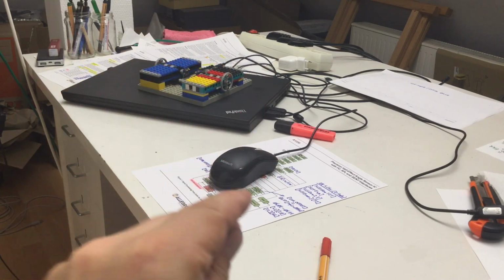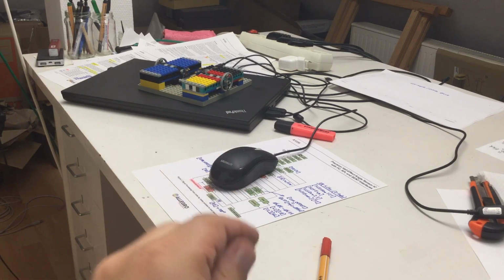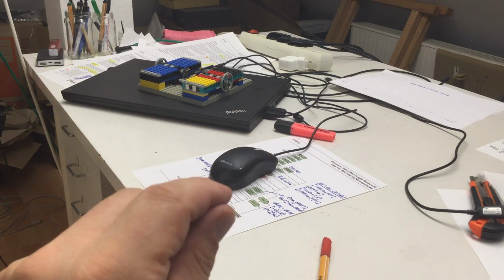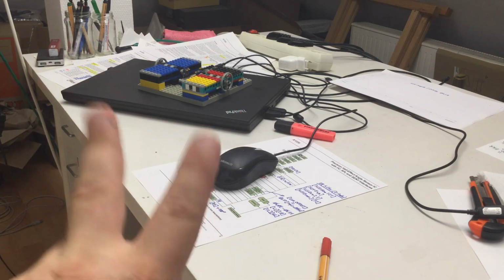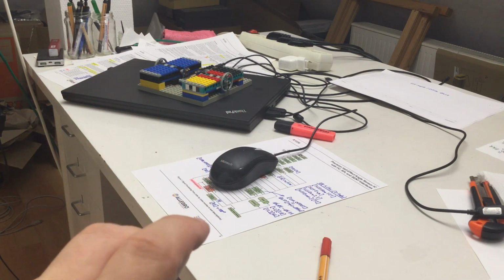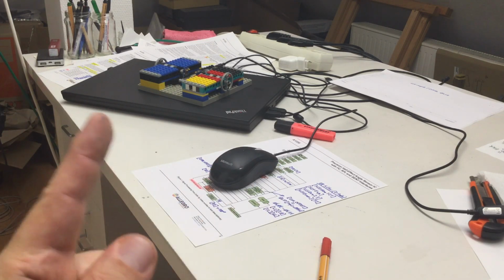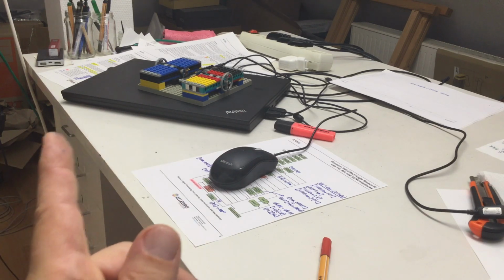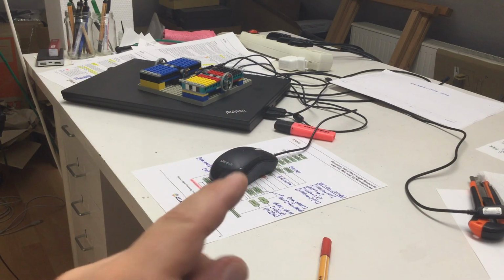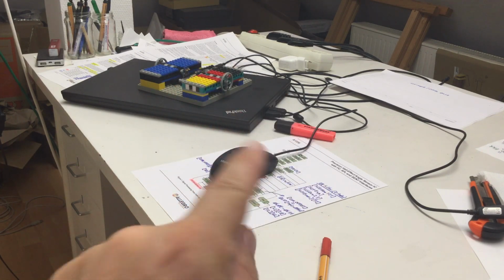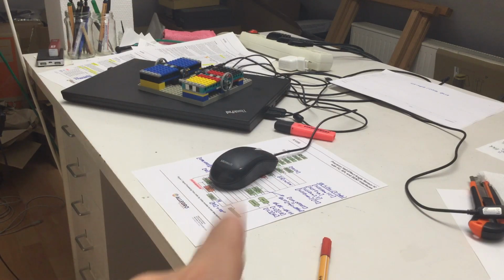But anyways, next time we will start to tackle, because I'm very interested in that, the linearization stuff, and we'll probably start off with the two pre-linearization options. That is to set a 0 offset to tell the chip what we want to be 0 degrees, and to tell the chip if it should increase the angle going clockwise or counterclockwise.